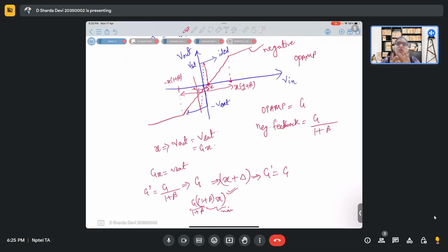So, noise. What do we understand by noise? It is a high frequency signal, and generally it has very small amplitude. If you see very carefully, after we have extended our range of inputs, we've actually reduced the gain. So it will also reduce the gain for my noise. Earlier, with an ideal op-amp, due to its high gain, even the noise was getting amplified by that amount. But now the noise can be controlled.